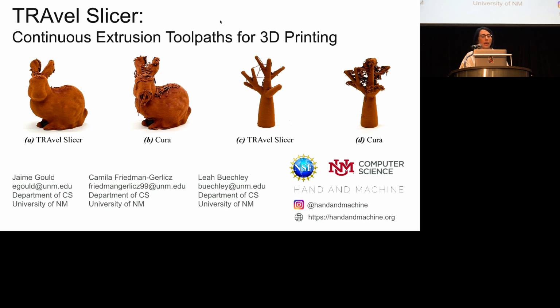It did require an extended nozzle, so it was a slight modification, but we basically purchased one online that was 30 millimeters in length and approximately 14 millimeters in width. We just installed that on the Creality Ender 3, and we had to increase the temperature to about 225, which was a really good temperature for heat loss as it went down the nozzle, but otherwise it worked just fine. Cool, awesome. Thanks. Great work.